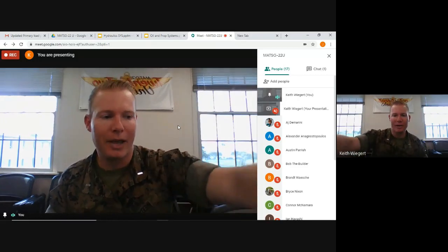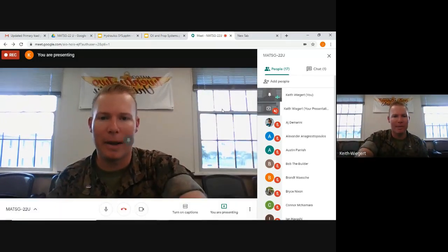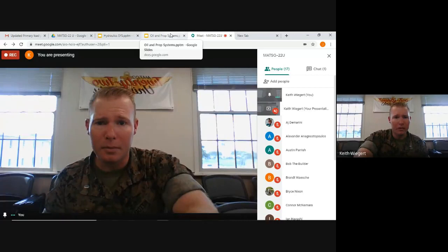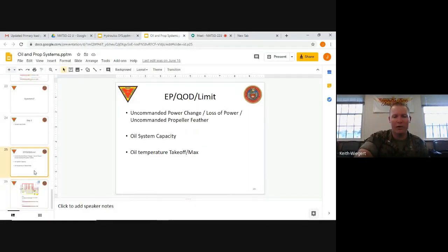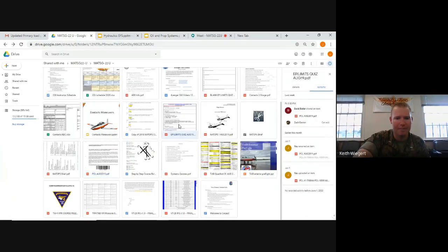All right, so we're gonna go ahead and jump right into it. Starting with the oil prop system, going over the EP of the day, the question of the day, and the limit, right? So let's hit the question of the day and the limit real fast. The oil system capacity, remember that's going to be 18.5 quarts, right? And the oil temperature for takeoff at max. Let's look at the limits page over here.